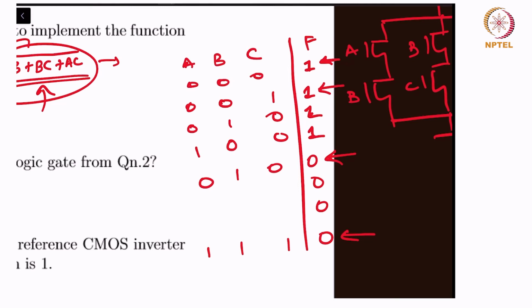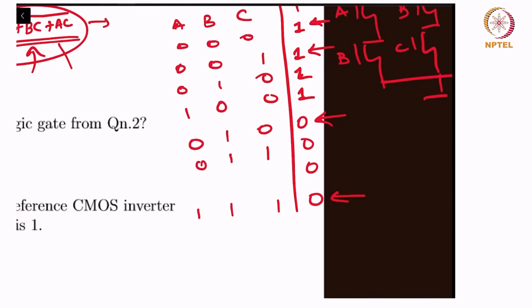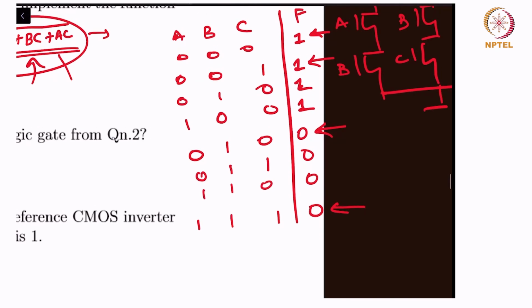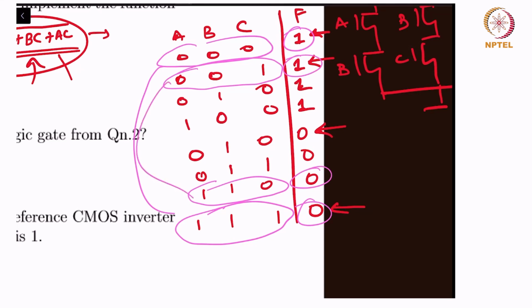And it's not that I'm just filling these entries here. These are the actual entries of the truth table. 0, 1, 1, right? Two of them are 1, so there'll be a term over here that becomes 1, so the complement of that will become 0. So for every term here that is 1, you have a term here which is the exact bitwise complement of its bits, and whose output is also a complement, right? For 0, 0, 1 you have 1, 1, 0. 1 to 0, that's complemented.